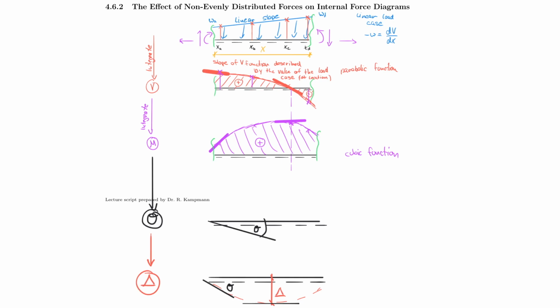And why is that important? Because engineers often build critical structures where the deflection needs to be limited. For example, if you have ever noticed that the shopping malls have huge shopping windows, then you also have seen that there is a very long span length, and of course the longer the span is from left to right, the higher the deflection can be. So engineers need to ensure that this deflection does not get too large, so that the beam would actually push on the glass beneath it. So the glass really needs some breathing room because it's so brittle, and engineers have to make sure that the deflection value stays within certain limits and keeps some room between the glass and the beam.